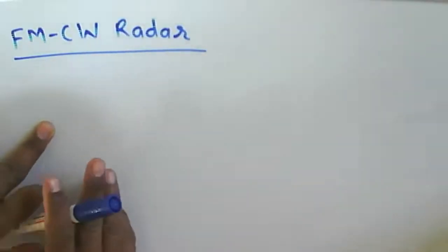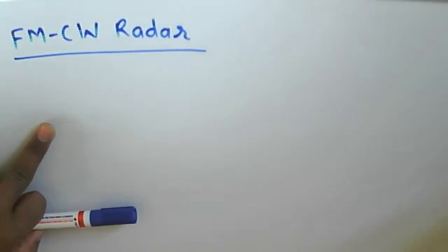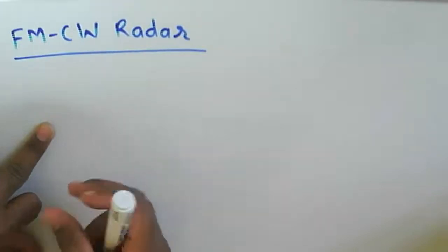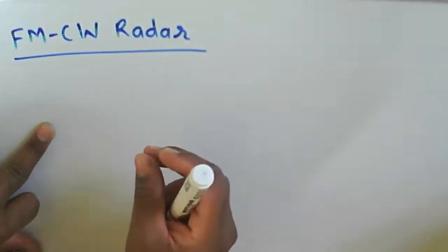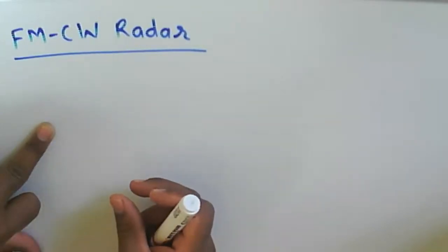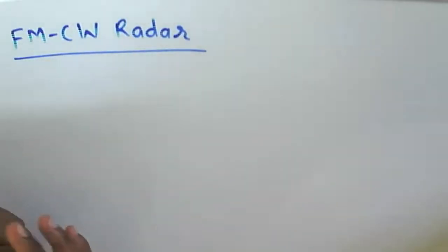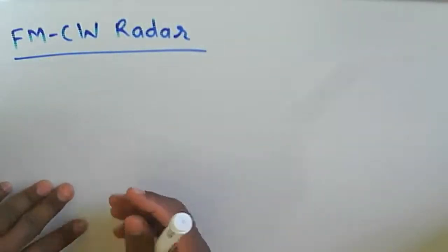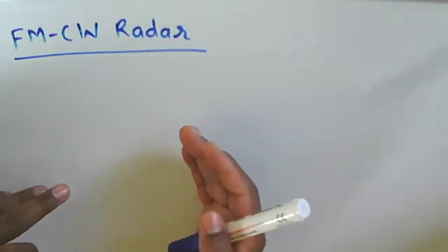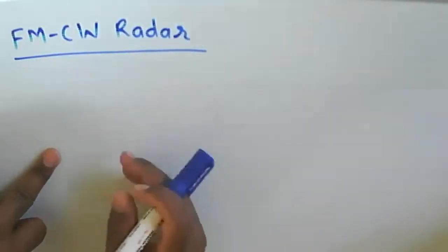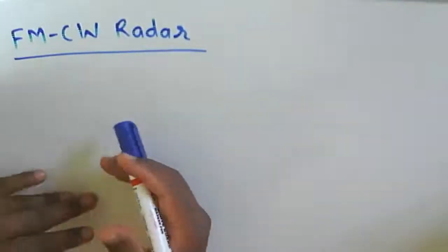The pulse has to be a narrow one, but we can do accurate measurement using amplitude modulation. But then there are limitations for the spectrum, because we need to transmit a narrow pulse. So that's why there will be limitations about the spectrum. Again, another issue is the timing of the transmitting signal. So instead of that, we are supposed to use a frequency modulation